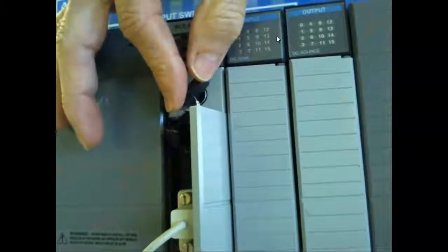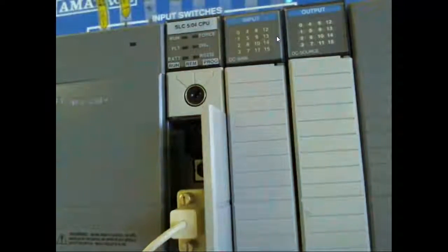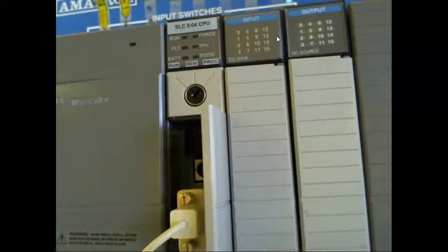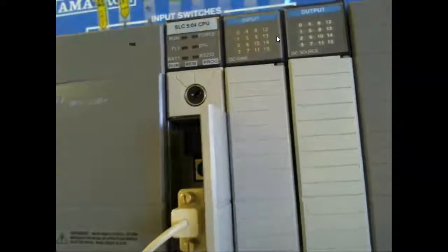This has a switch on it, which is pretty nice. We can switch it to program, or switch it to run, which tells the PLC to run the program. Another position is called remote, which means you can switch it between those modes from your computer. What's nice is that you can take the key out so somebody can't change it. If it's in run, they can't come in.